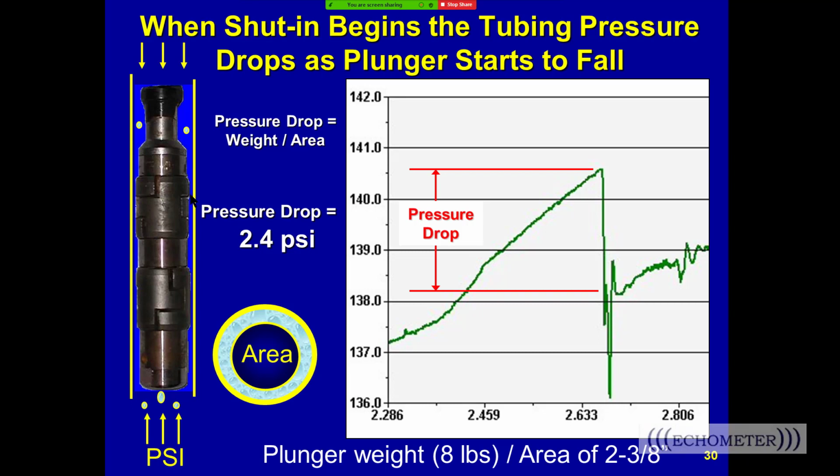So the first thing you should do when you're sampling at high speed is sample in your office for the time, maybe the hour, that you plan to track the plunger, and make sure your computer will handle all that data. It's a lot of data, 480 samples a second off of tubing pressure, casing pressure, and acoustic signal. It's a lot of data. So no, you have to set the time when you start the test.